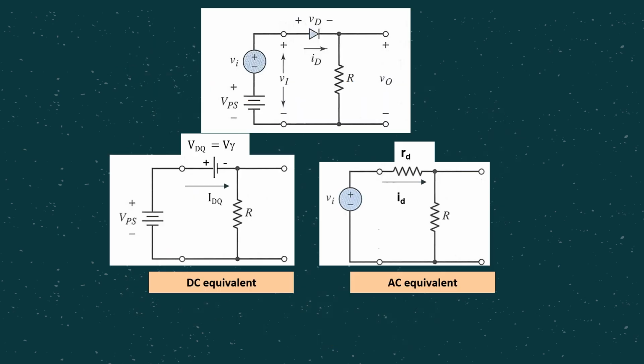So basically for the diode AC analysis, if you can see from this circuit, the diode is connected to both signals, right? VI is the AC and VPS is the DC. So in order for us to do the analysis, we can do the DC analysis first, then later the AC analysis. And in this case, we can apply the superposition theorem, remember? Whenever we want to do the DC analysis, first we turn off VI, make it short circuit. So in this case, we are considering only VPS when we do the DC analysis.